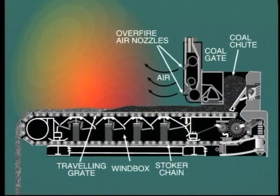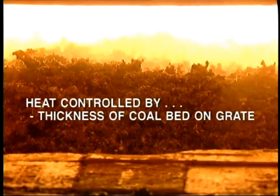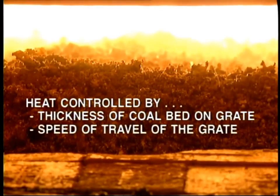As the grate continuously moves forward, the coal on the bed burns, leaving ash to be discharged into the ash pit, as the grate follows its continuous path and returns again to the coal feed. Control over the heat input to the boiler and consequent steam output is affected by adjusting the thickness of the coal bed on the grate and the speed of travel of the grate. The correct distribution of air is vital if complete combustion is to be obtained.